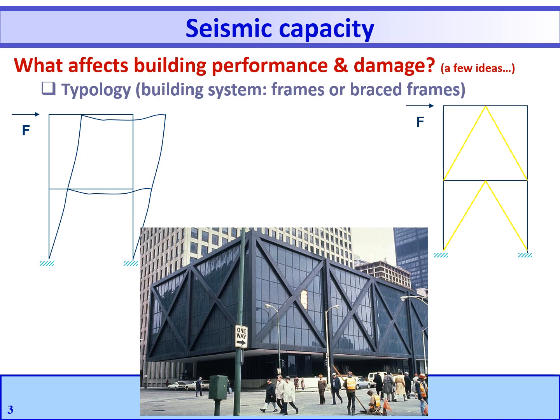As you know, and as we have discussed before, the primary intent of all seismic code provisions is to protect the life safety of building occupants and the general public through the prevention of structural collapse from a natural event such as an earthquake. This goal encompasses some objectives. We start from the small or moderate earthquakes, for which the target is to control the severity of the damage. Another goal, one step upwards, is to resist a minor level of ground motion without damage.